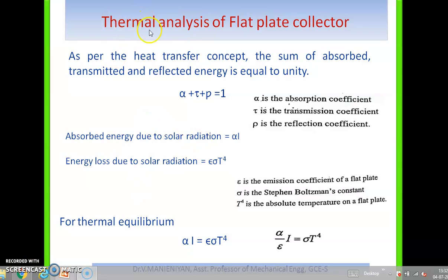So now we discuss the thermal analysis of flat plate collectors. Normally, a body is subjected to solar radiation of some intensity. It is partially absorbed by the body, and the remainder is transmitted and reflected. As per the heat transfer concept, the sum of the